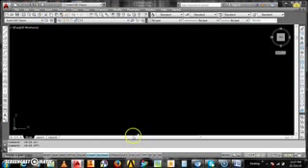First in AutoCAD, we define the page length. To define the page length, we will set the limits. In this panel, we will write LIMITS, limits, enter. Like we are specifying our page, we will specify the coordinates x and y. This will be the x and this will be the y. In the x coordinate we will define 0 and in y we will define 0. So the page starts from here, and we will press enter.